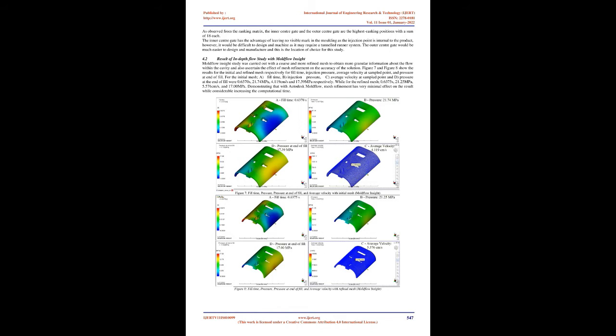A second study was carried out with a more refined mesh of length 0.25 mm, resulting in 144,058 elements, to ascertain the effect of mesh refinement on the study. Analysis was carried out on both studies after specifying process parameters similar to that of the injection location study. As a dedicated injection molding software, Moldflow Insight provides sensible defaults for most of the meshing parameters. Ansys 2020 R2 was utilized for the study.